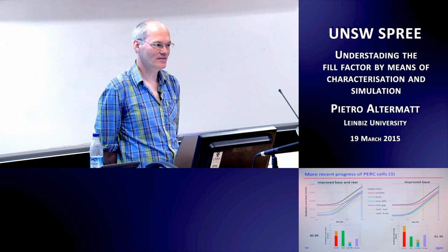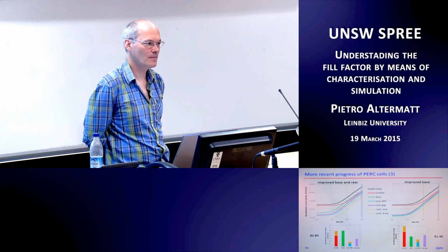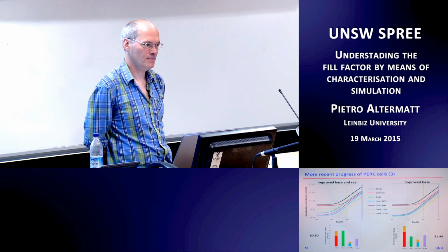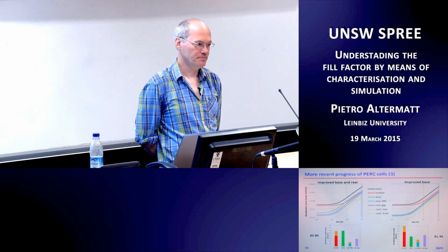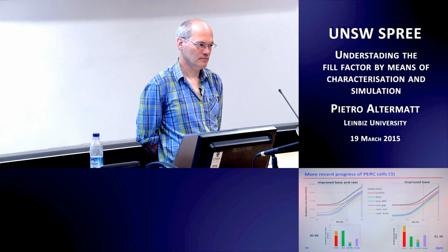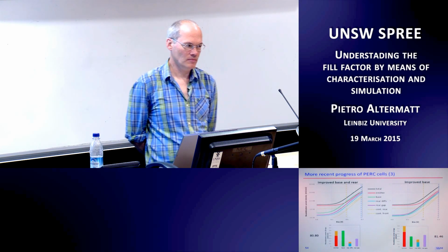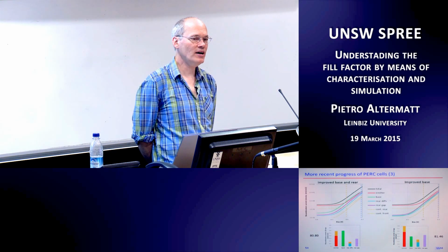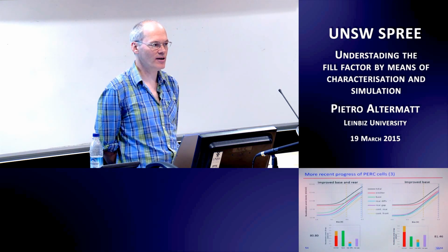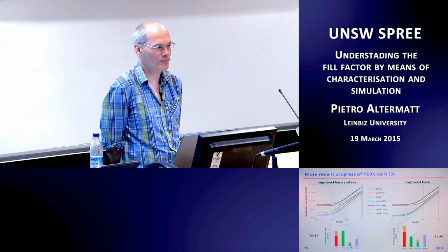I'm wondering whether in the ideality factor is where everything is hidden. So once you extract that voltage-dependent series resistance, that resulting ideality factor is really not the ideality factor of the diode, but the fact that the J naught is changing, right? Mm-hmm. So if we know that the ideality factor should be 1, then we could figure out how the J naught is changing to give us the ideality factor that we measure. Yeah. And then from there actually be able to build this. I find the properly corrected IV curve very important for the understanding, and this is done purely experimentally.